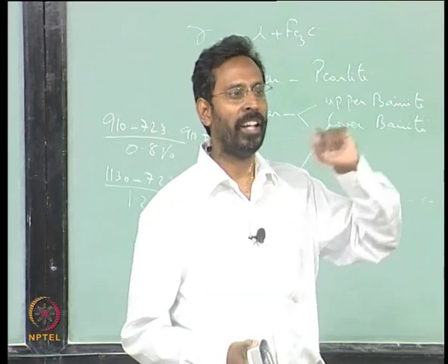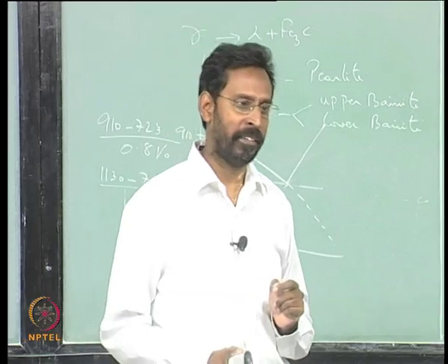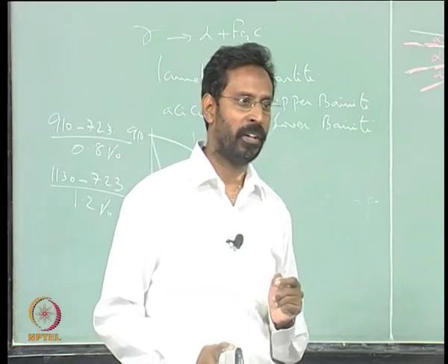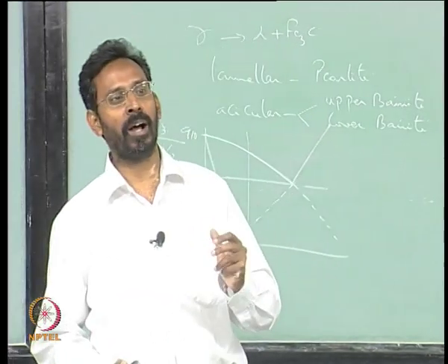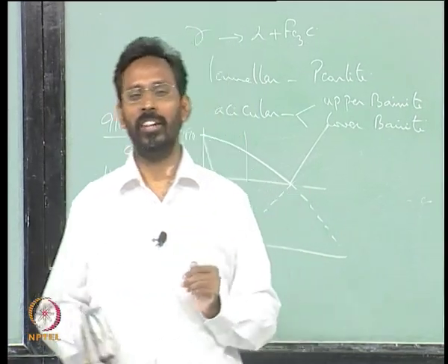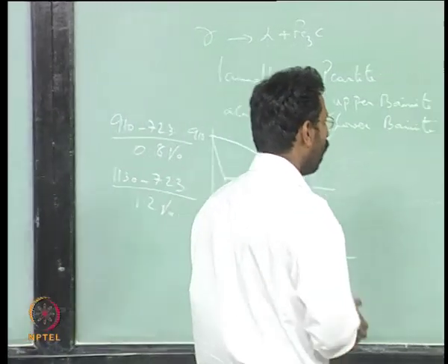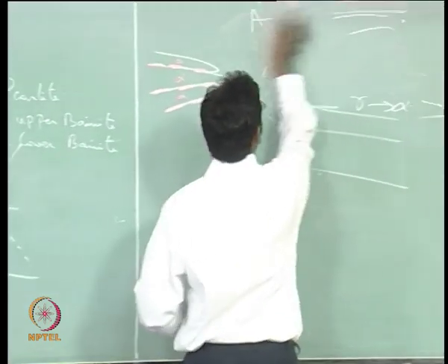When you take a high carbon steel, there is a pro-eutectoid cementite coming out, and the moment it comes out, it can nucleate pearlite. So there are always issues like that. That is why, interestingly, if you have ever seen the TTT diagram,